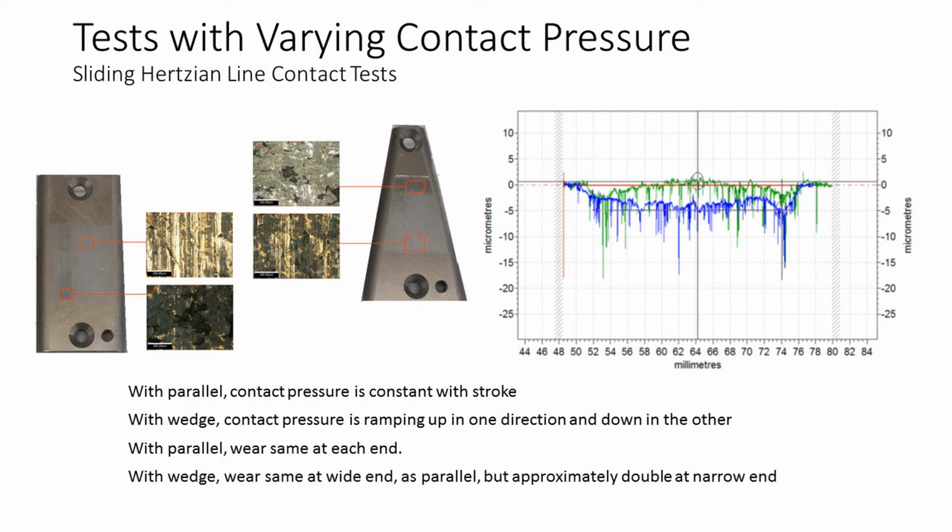However, changes in instantaneous contact resistance is a good indicator of wear transitions. With a curved edge wedge specimen, it is possible to generate different wear regimes at either end of the specimen, hence provide much more information from a single test run. It is possible to produce mild and severe adhesive wear while running under conditions of steady load and temperature. In other words, without resorting to the application of either ramped loads or temperatures.